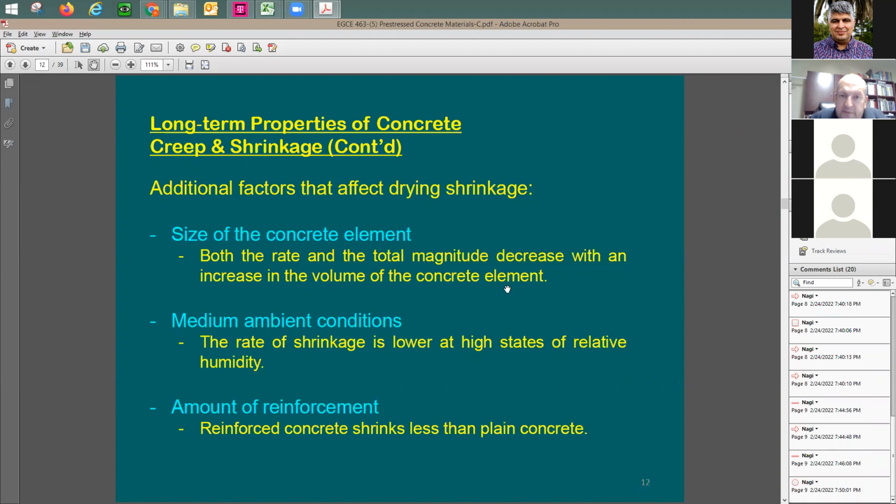I say, well, Arizona is going to be very dry. Drying process is going to be faster. And generally speaking, when it's very dry, it means that you're going to be losing lots of the moisture inside the concrete very fast. So I would say, of course, in Arizona you're going to have more shrinkage, meaning more losses. This is going to be a problem here for you.